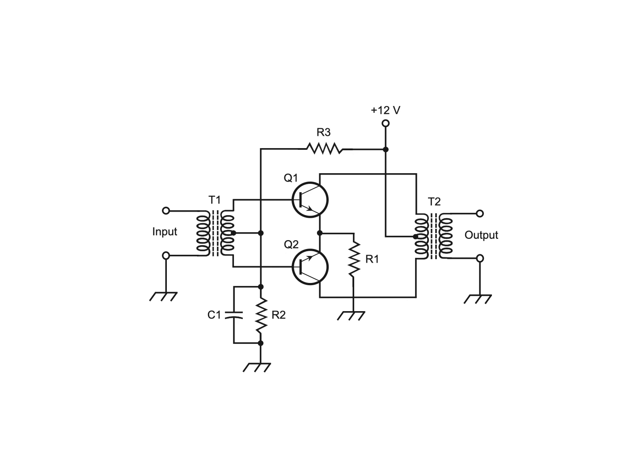One of the transistors amplifies the positive half of the AC audio wave, and the other transistor amplifies the negative half. You might say that Q1 does the pushing and Q2 does the pulling, so that when you combine their outputs, you get an amplified version of the complete audio input wave. This circuit will accept the output of a low-level audio amplifier and boost it. However, the output from the original crystal radio would not be enough to drive the power amplifier. When you hear the term power amplifier, you should remember that the circuit does exactly what its name implies. It takes an input signal with a certain amount of power and produces an output signal that has more power.